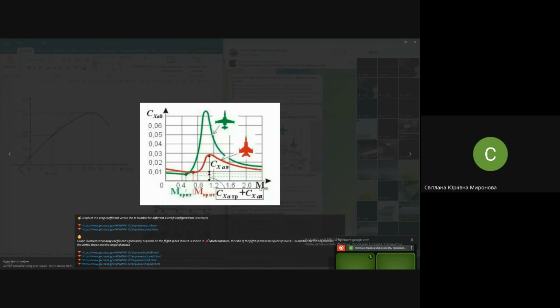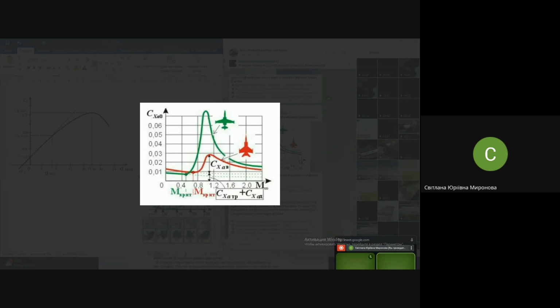We'll explain. And also what we might see, it depends on the shape of the airplane, as it's visible here, but also depends on the shape of the wing itself. Not even, in this case, the shape of the profile. It's the outer shapes of the airplane, the outer shapes of the wing. So drag is a much more complex matter than it seems, at least a much more complex story than when we're talking about the coefficient of lift.